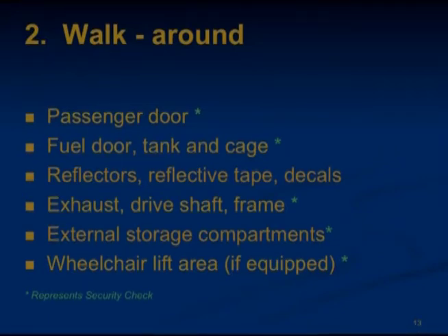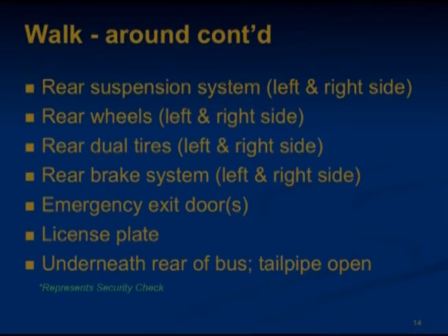External storage compartment, if your bus is so equipped, make sure that it has nothing unusual present. And for wheelchair lifts, if so equipped, make sure that the doors open and close and latch properly. Make sure the lights work and nothing unusual is found. Continuing with the walk-around, check the rear suspension system. Sight check it. Does one end of the bus sag?